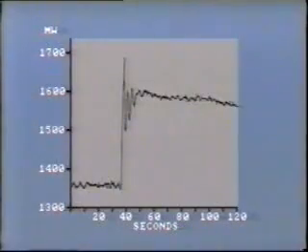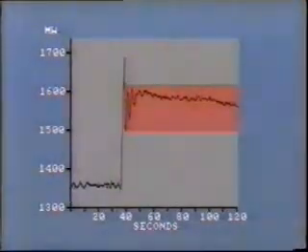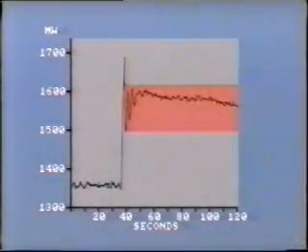This trace shows megawatt flow into the area. The inflow immediately increases to supply the loss. But before the remaining generators settle down to their increased megawatt outputs, you can clearly see some oscillations. Most oscillations like these are well damped and die out in a few seconds.